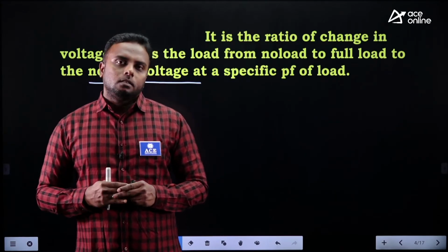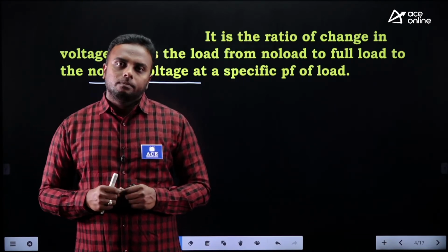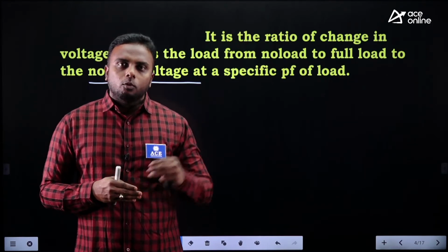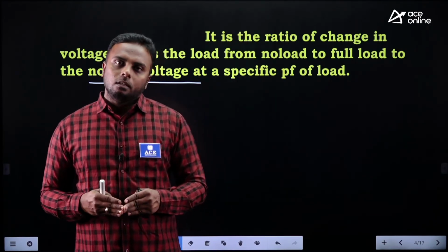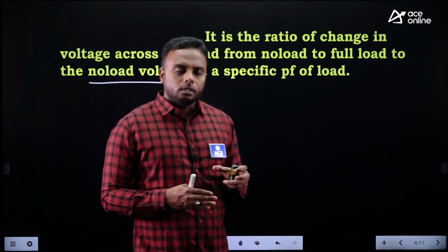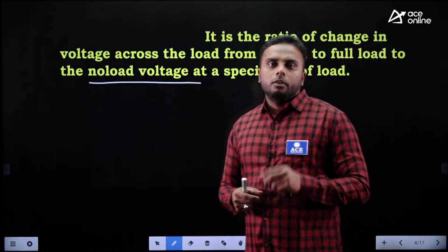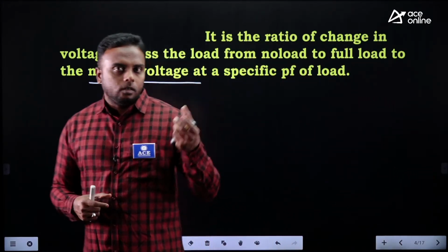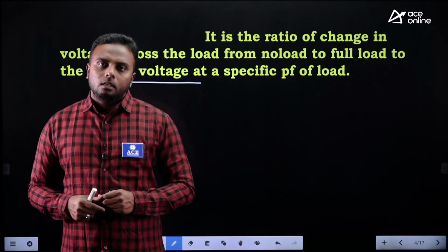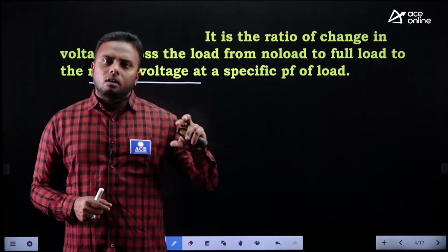At low voltages, generally the loads, particularly motors, will draw high currents. When we get low voltage, most of the voltage drops in the transformer itself. Under low voltage condition, loads will draw high currents, then overheating of these motors takes place. Overheating means they may get damaged. That's why we need to maintain a proper, almost constant voltage to loads.